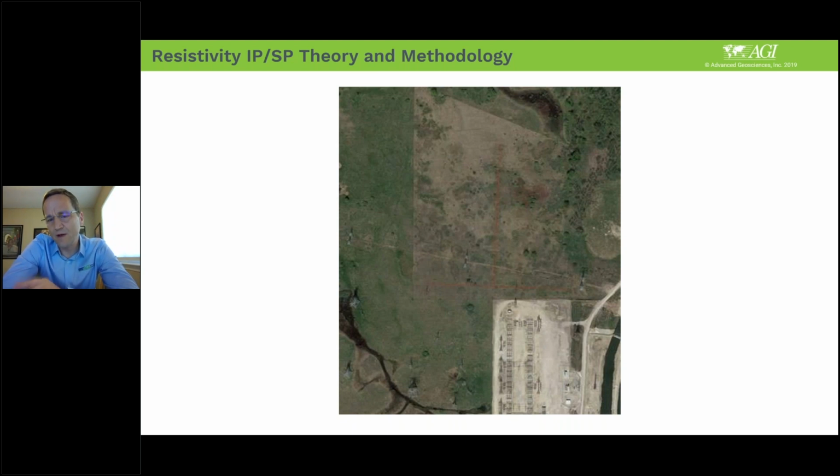Even though the Wenner is typically very smooth and kind of averages everything underneath that central point, this area here and this area here did not have the same values. And what it was, was the grounding between these towers. For lightning protection, they are grounded to each other. So this one here, the one going probably north-south or vertically here, is the more accurate one. This one is influenced by the metallic infrastructure, by the grounding between these towers.